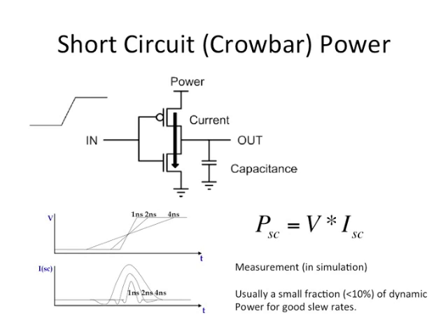Now whenever I am switching a gate, besides the power to charge and discharge the capacitance at the output of the gate, what happens is that when I am switching, the input is transitioning from one logic state to another. For example, it could go from logic 0 to logic 1, where the voltage is going from 0 to VDD. When that is happening, for the duration in the middle, both the NMOS stack and the PMOS stack will be on for a short duration.